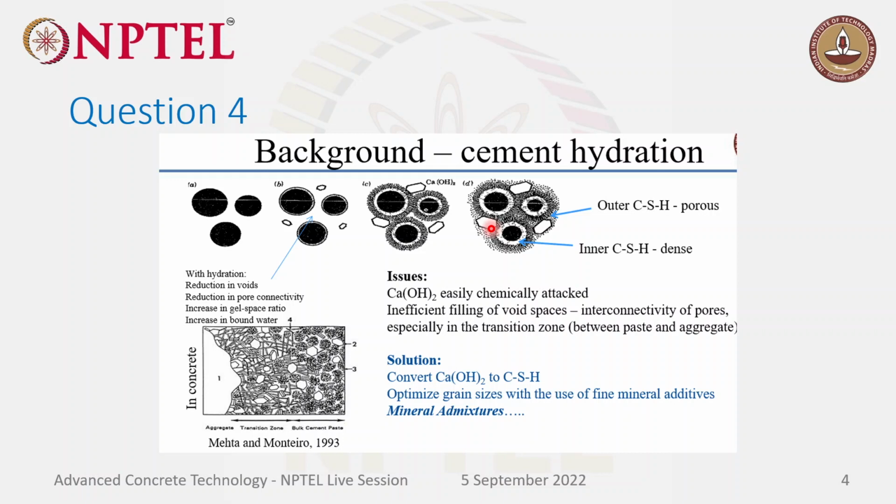From soil we can have sulfates, right? If it's near an agricultural field, then it will have more gypsum. Such things will come and react with the Portlandite to form sulfate reaction products that will affect the durability of the concrete. That will be taught to you in a later stage of the course.